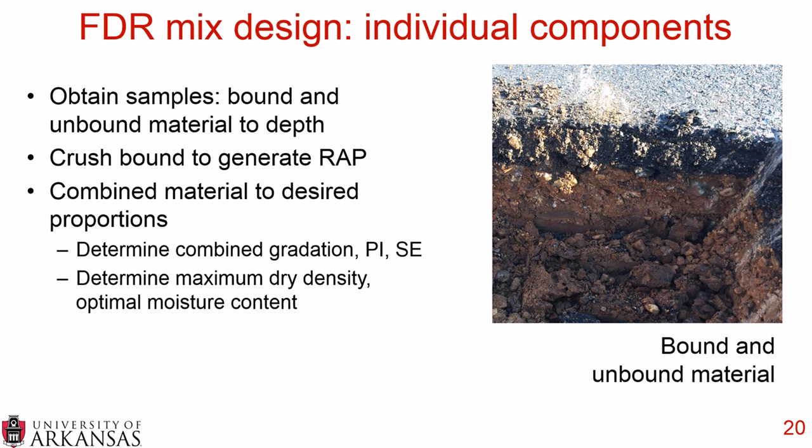And you want to determine the combined gradation of that bound and unbound material, the plasticity index and the sand equivalent limit. You want to determine the maximum dry density and the optimal moisture content, and that can be done with a proctor or a modified proctor. And then you want to perform tests on the mixture of components.